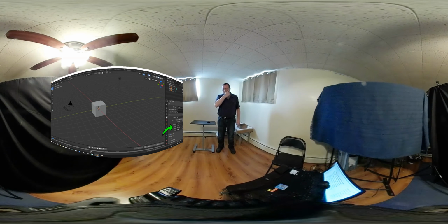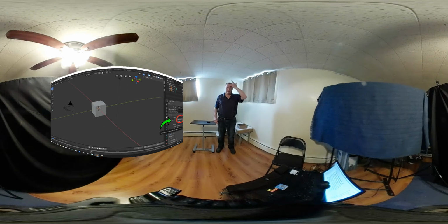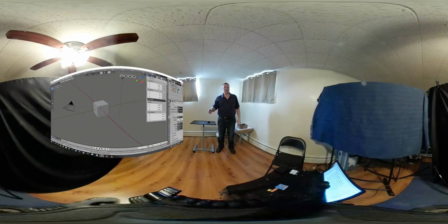And the other thing we got to change here is the unit scale. It says 1.0. We want that to be 0.001, and that should accurately present our cube and objects where we need them to be. So once we hit the letter N again, and it gets rid of that panel, we do see that cube. Well, if you hit N right now, it shows it as being at 2 millimeters. But go ahead and hit N again, get rid of that.